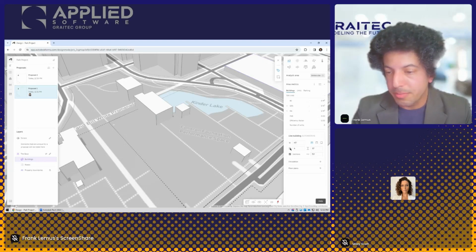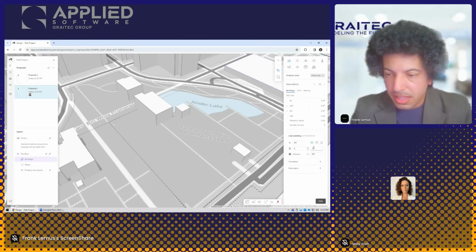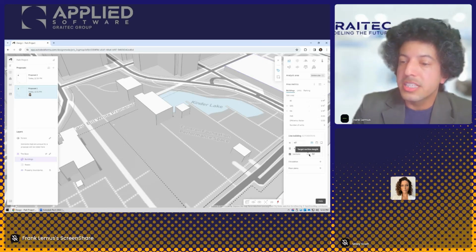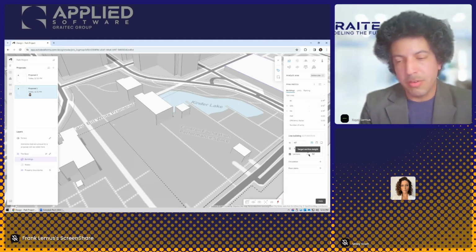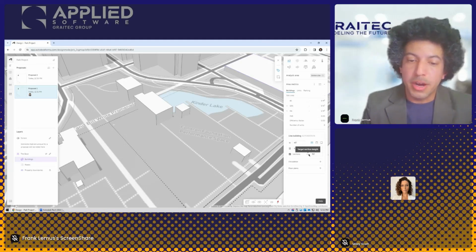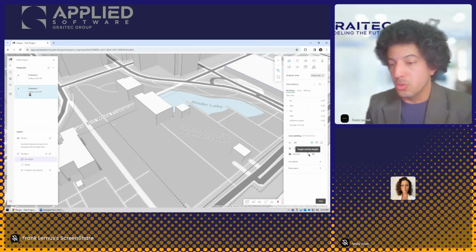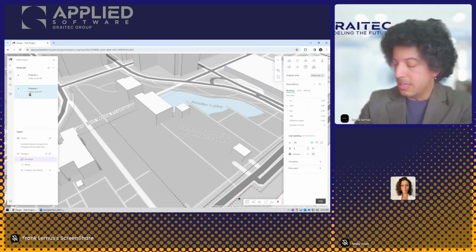See, you've got the width, you've got the number of floors. These are all defaults that I'm setting right now, but of course I can change them later. The story height, I usually like to say 12. That's a little bit more realistic, I think. And the section length. In other words, how often will Forma, I keep wanting to say Revit, how often will Forma break the model to subdivide it as an individual unit? Okay, and we're going to look at circulation and floor plans in a second.